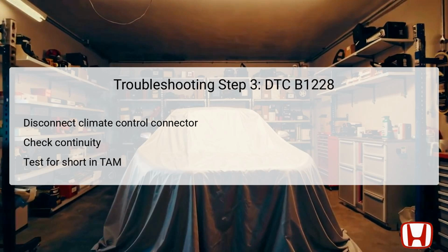The first test point is located at pin number 18, blue fault, of the climate control unit's 32P connector, and the second test point connects to body ground. The test conditions should have the ignition switch in the lock position and both connectors disconnected.